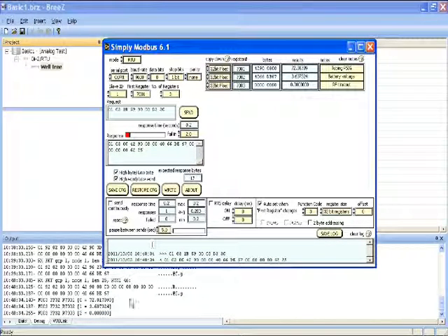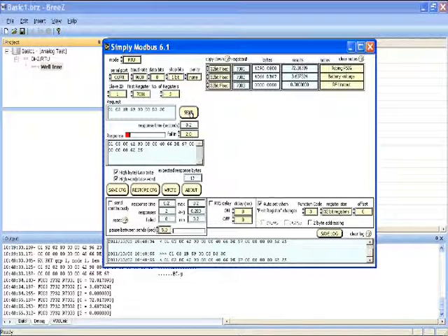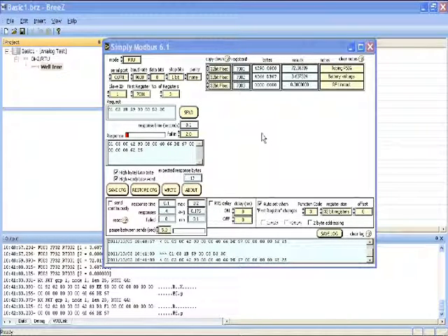Notice when I do, in my debug window, I can see the response from the DH2. 7001, my pressure has bled down to 72. 7002, I have 3.6 volts, and 7003, I do not have an RF timeout. If I did, that would in fact be a 1. And every time that I send this request block, I see the response happen in the debug window. You can also clearly see that my Modbus master has been populated with the proper registers in the proper location.